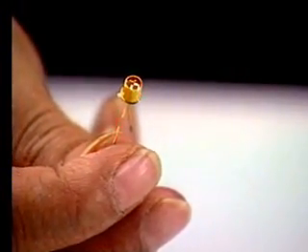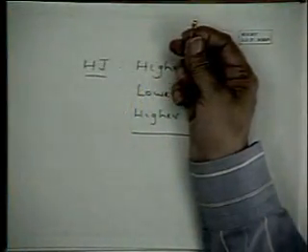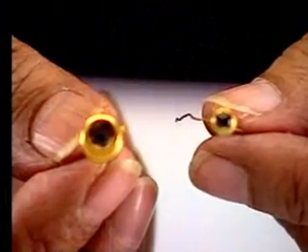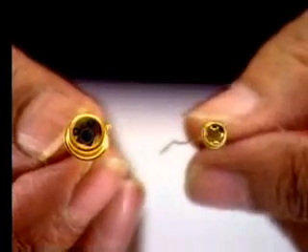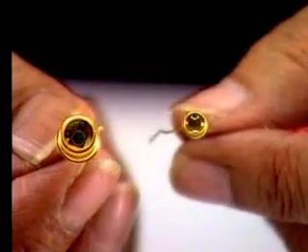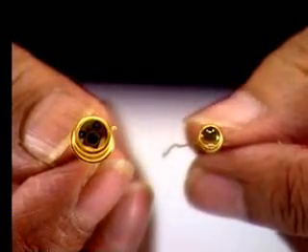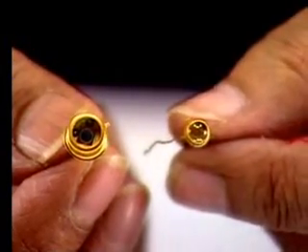In order to reduce the RC time constant, the area is made very small, and you can compare the two PIN diodes. These are both silicon PIN diodes, which have very good response in the gallium arsenide wavelength range. So they're very useful in detection up to about 1 micron wavelengths.